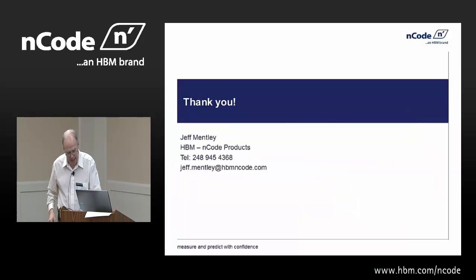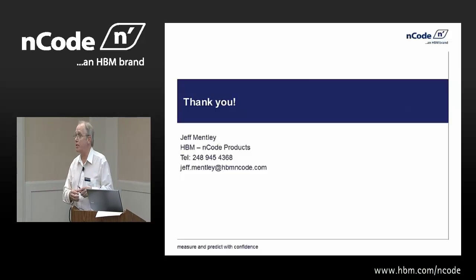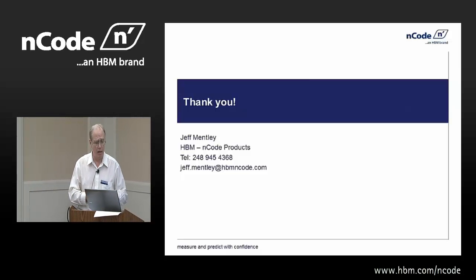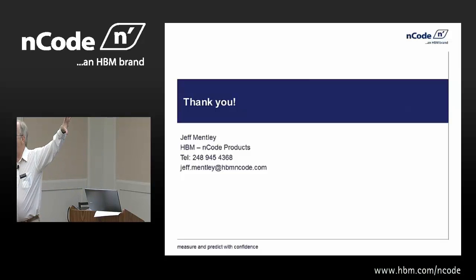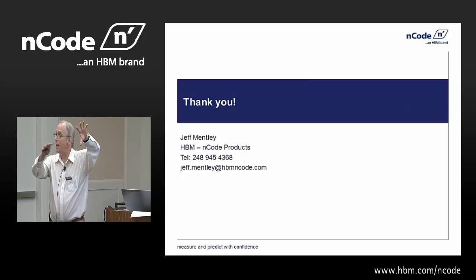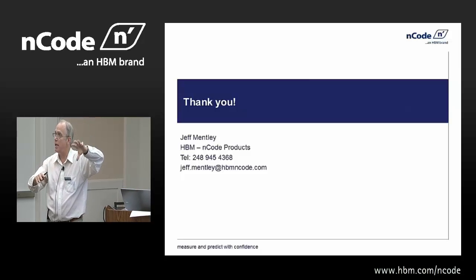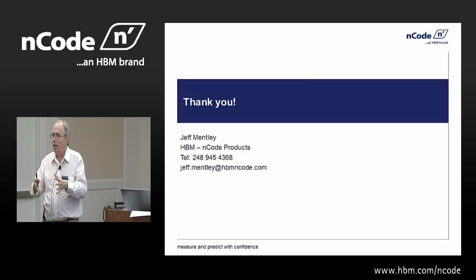This, again, is very easy to program in terms of duty cycles. I could set up an analysis where I have not one vibration fatigue analysis, but 3 in a duty cycle. 3 different PSDs coming in, 3 different harmonic analyses coming in, 1 in the X, 1 in the Y, 1 in the Z. And I can very easily program this to make it look just like the shaker table test that I would do for 3 axis. Okay?